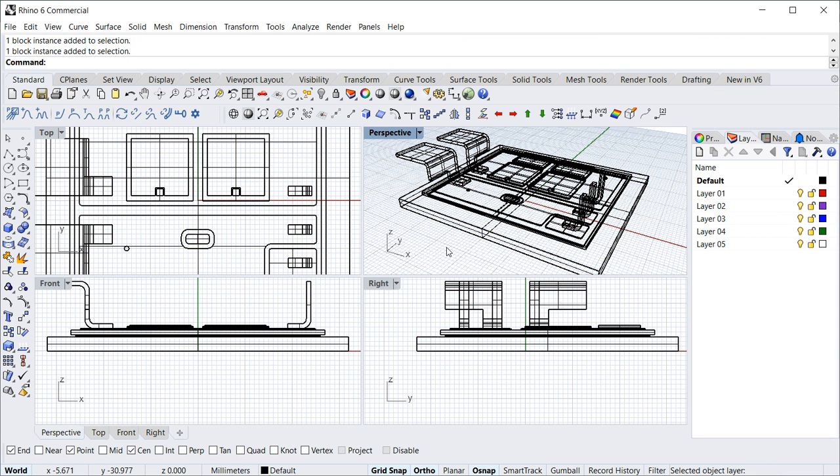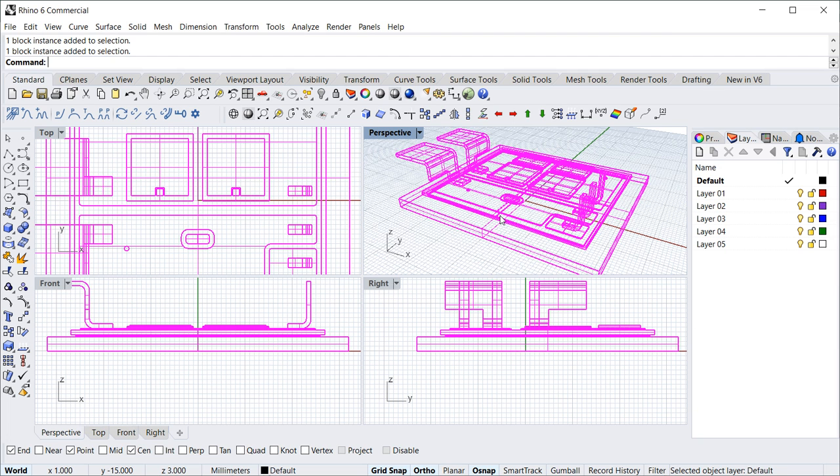And this is, for instance, when you import it from Inventor, where you have an assembly that uses sub-assemblies, and these sub-assemblies have then finally parts. And this assembly structure, hierarchical structure, is organized within Rhino using blocks. And one block is just the whole assembly. We'll later see how to get rid of this block to access the individual objects.